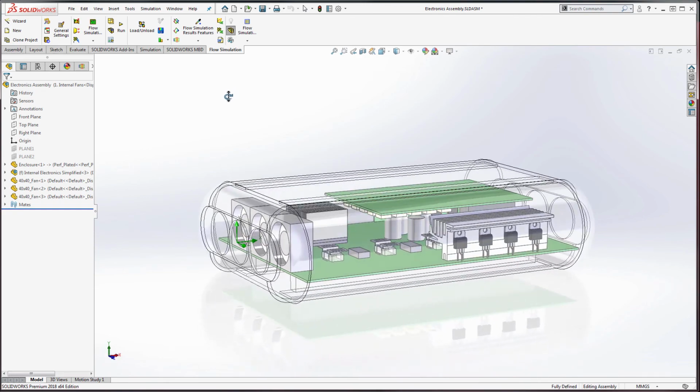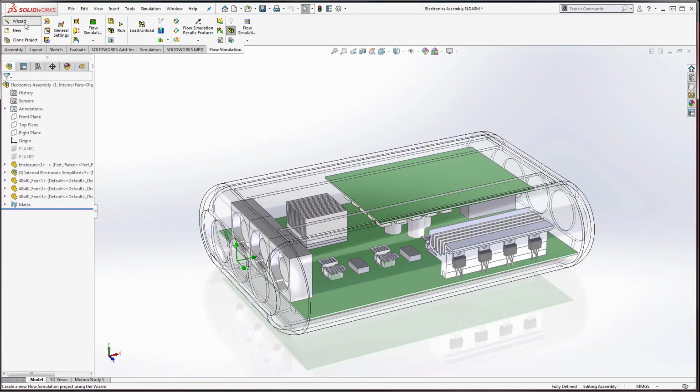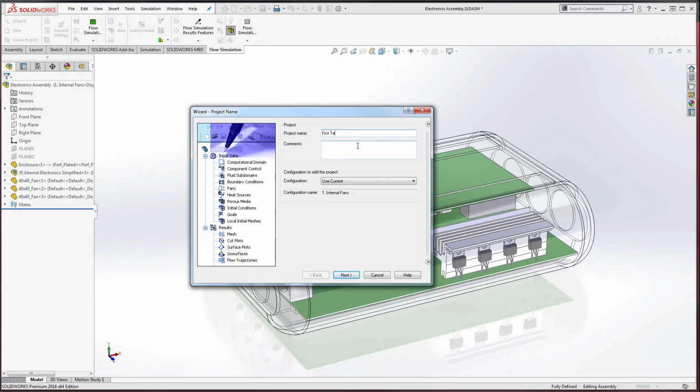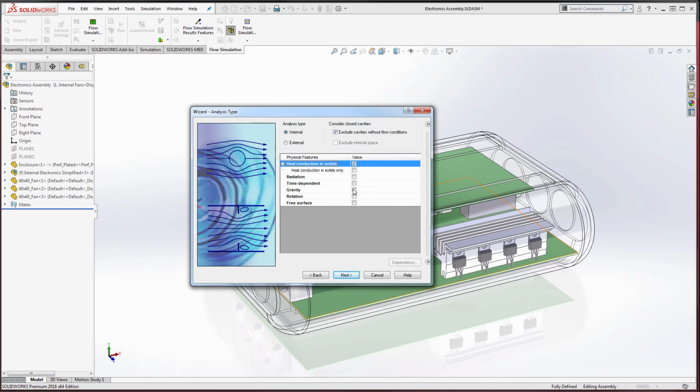Okay, our product design is underway, but we need to assess some contrasting ideas to go on. Customers are asking for less noise, but they like to have more power. This will be tough. So, let's go with the flow. We will try to minimize maximum thermal heat on the main chip and memories, and we would like to use as few fans as possible. The first step is to build the scenario that we want to analyze inside the Flow Simulation Wizard.